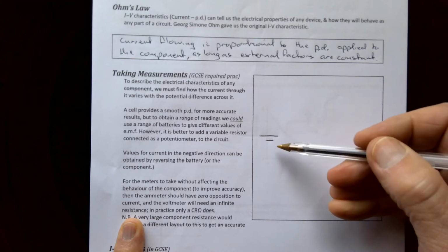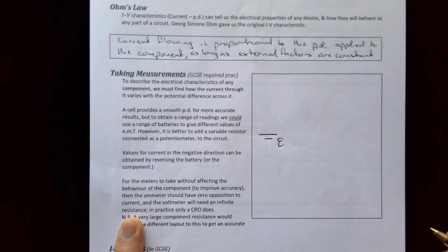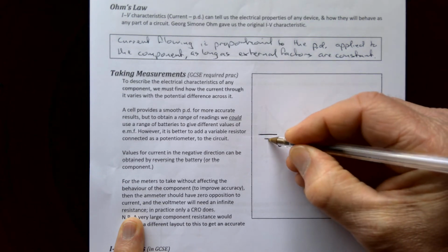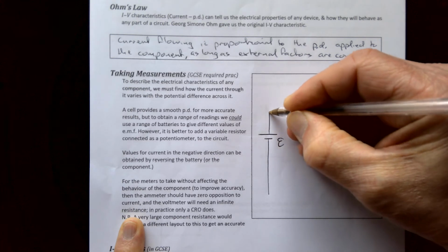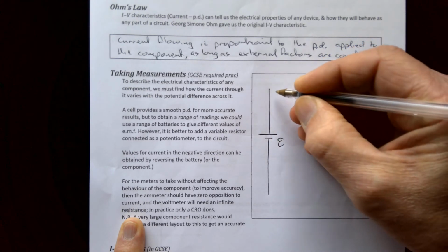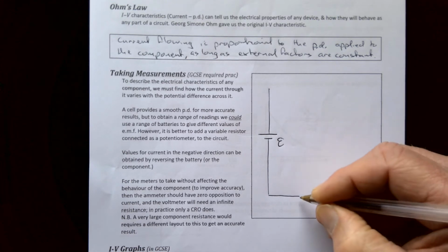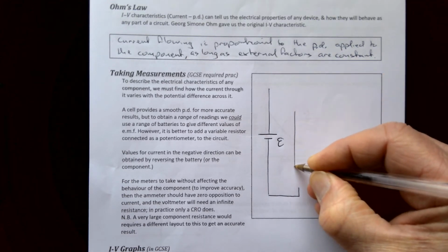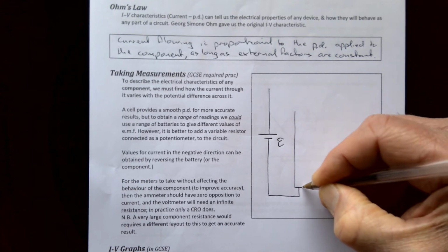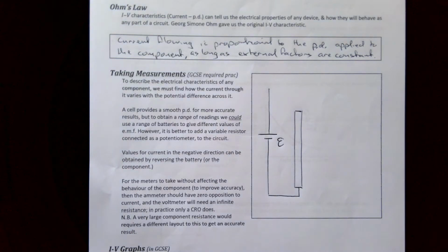So we need an energy source, and that is going to be our EMF, so I'm going to give it the curly E. Okay, so the voltage provided to the circuit, energy given to each charge. And then what we're going to do is run that through an adjuster. So we have something called a potentiometer, or given a different name sometimes, which depends on how you use it.